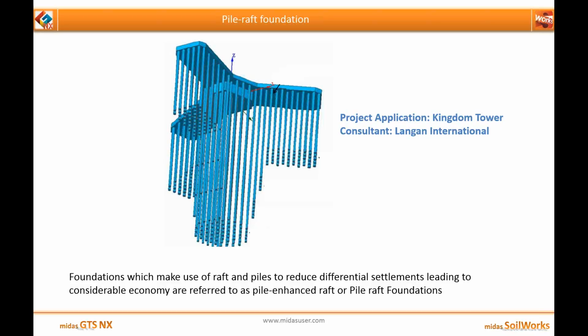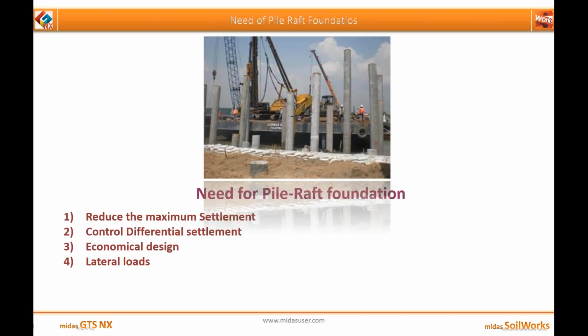First of all, about pile raft foundation, which makes use of raft and piles to reduce differential settlement leading to considerable economy, and is referred to as pile enhanced raft or pile raft foundations. Now, why the need for pile raft foundation? The first is to reduce the maximum settlement, control the differential settlement, and economical design. And whenever there are lateral loads coming onto the foundation, one needs to go for the pile raft foundation.